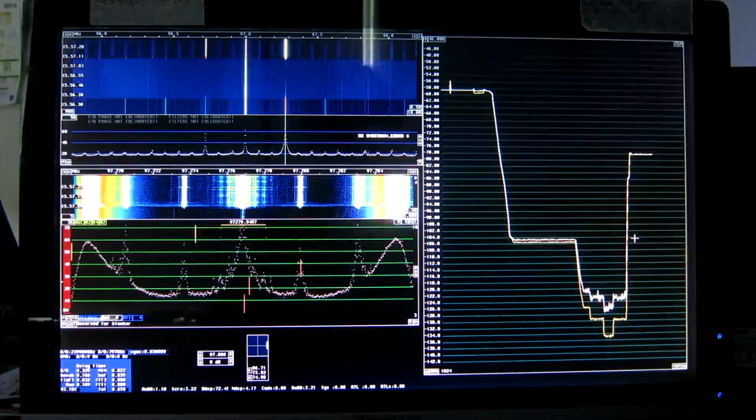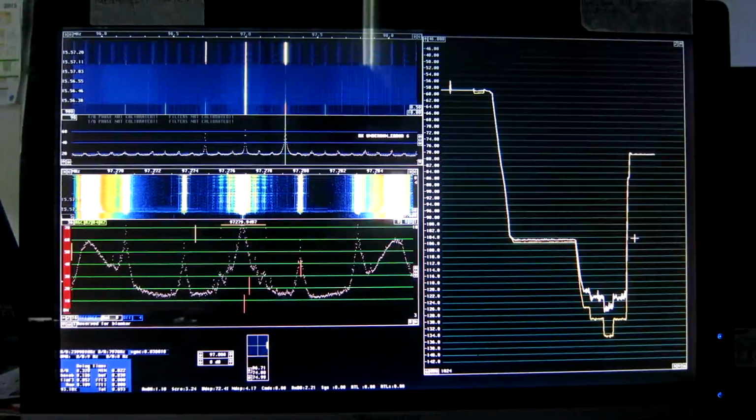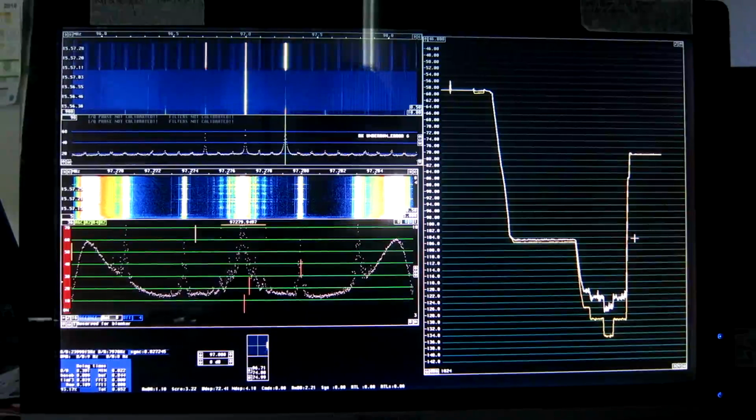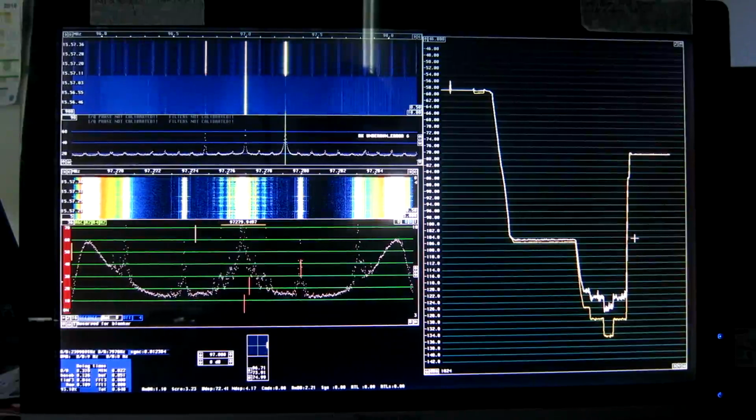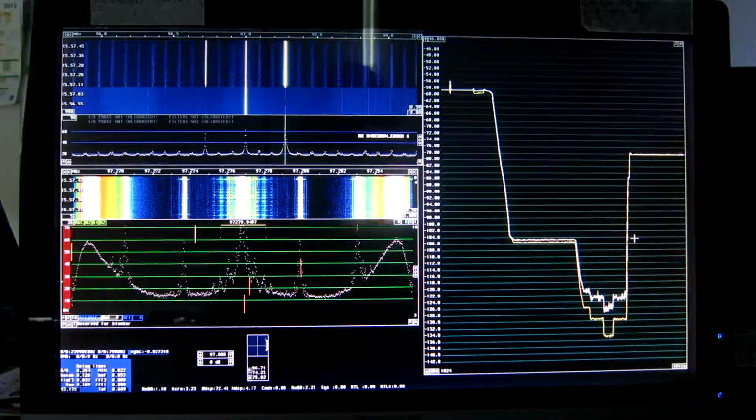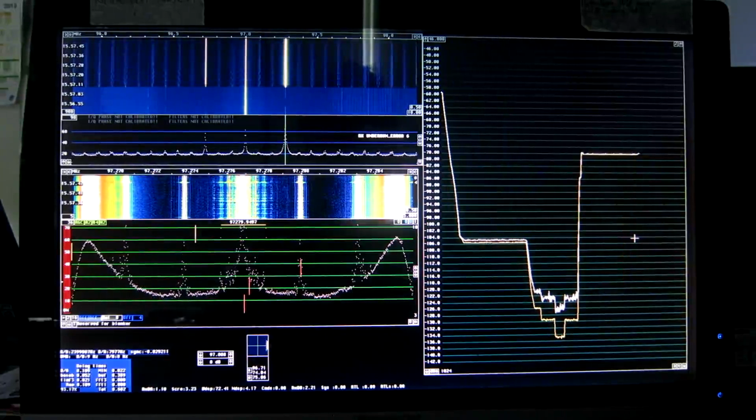Having the dongle in sensitivity mode at a gain level of 0 means there should be a preamplifier in front. Or in this situation, there should be other signals that would work as dithering. So this is an artifact that doesn't really cause much problems in real life.